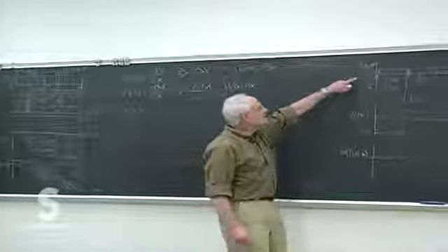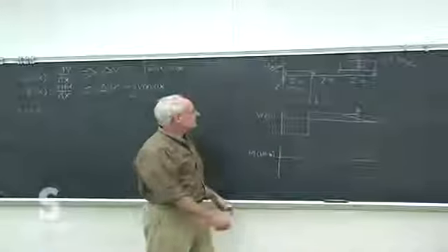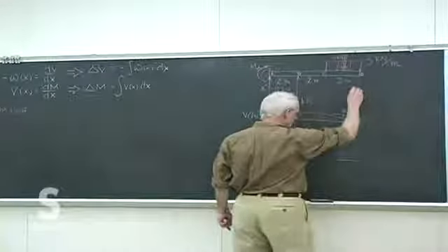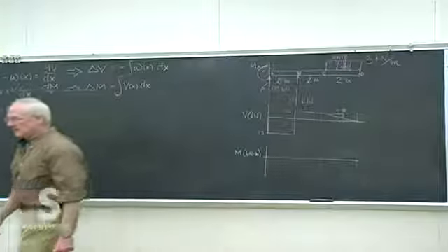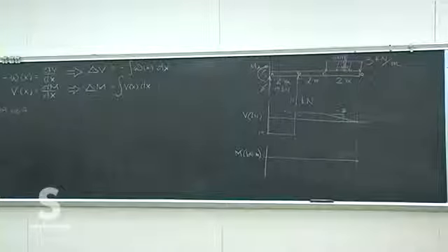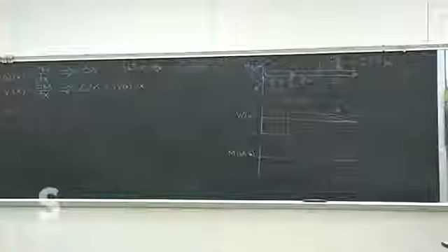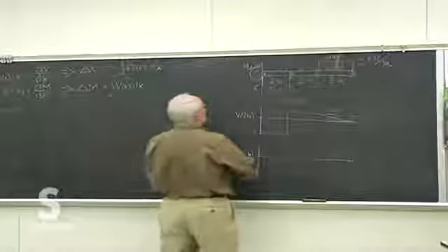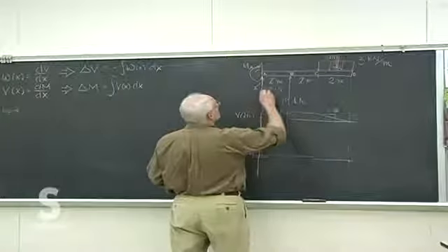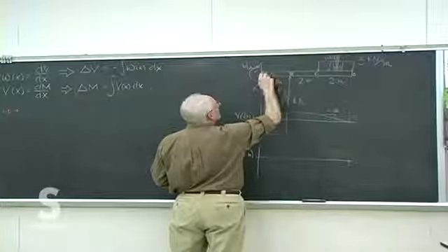We don't start with 0 moment, because we have the cantilever support there. We do finish with 0 moment because it's a free end. But a cantilever support will supply internal moment. What that means is right at that point the beam is already going to be curved some. The final shape of the beam will be horizontal.